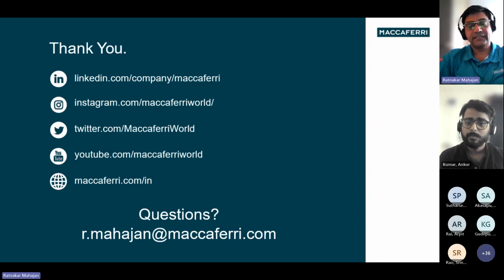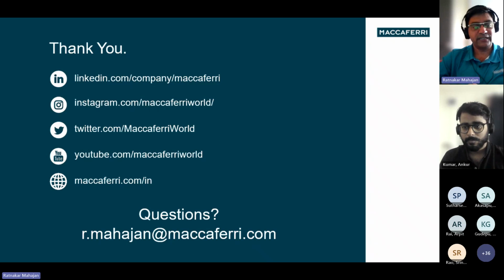Right, sir. Ideally, the earthwork shall be done, as I said, with a maximum 200 mm compacted thickness to 98%. Then usually we don't encounter an issue. Basically, the tallest embankment we have seen for a railway track is around 55 meters, near Katra, Reasi. That structure has a ballastless track, the first ballastless track of Indian Railways. And there were a lot of concerns that there could be settlements. Usually, as you rightly mentioned, if not properly compacted, there are possibilities of settlement.